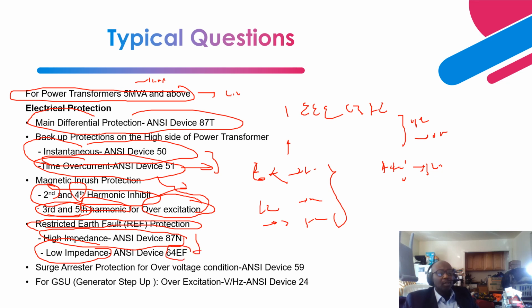Okay, so then you can further say that, because the main differential protection, let's say for a delta-Y ground transformer, cannot see faults right at the neutral of the transformer or at the ground point, it becomes very challenging to have protection in this region, let's say the last 5 to 10%, right?